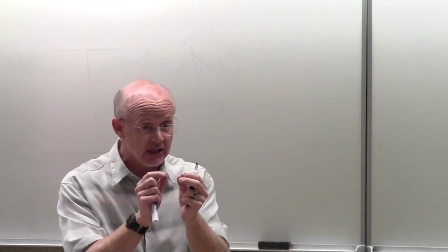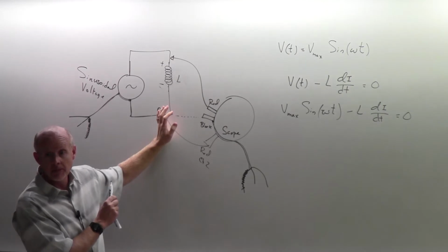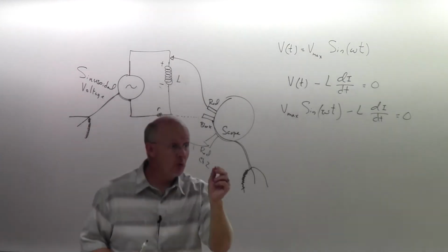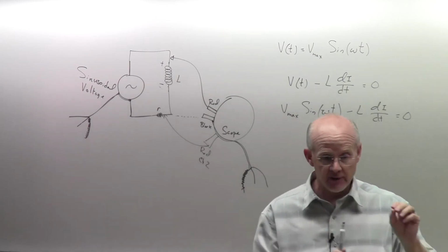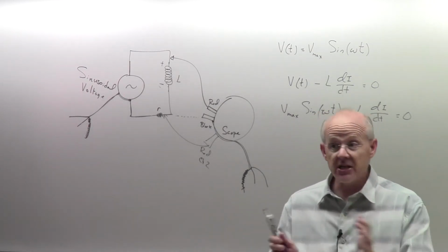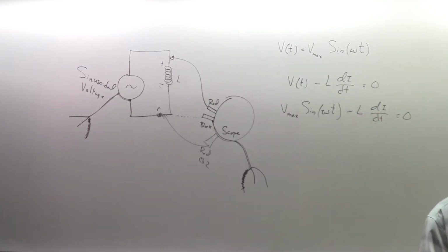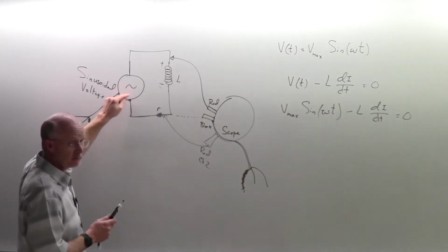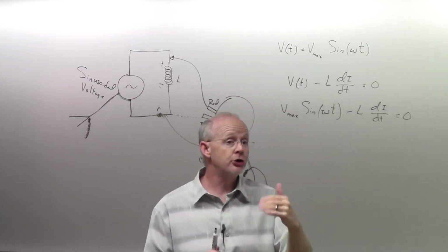It's not the resistance. Remember, this little resistor down here, you want to pretend like this one doesn't exist. This is small. This is only in here for the measurement. And I know that all wires have a resistance, but that is small compared to what I want you to see, which is that this inductor is opposing the current from coming in. Notice I didn't say resist it, because it's not resistance, but it is an opposition. There is something stopping it, and that's Faraday's law. And so as this thing changes, this creates an EMF.